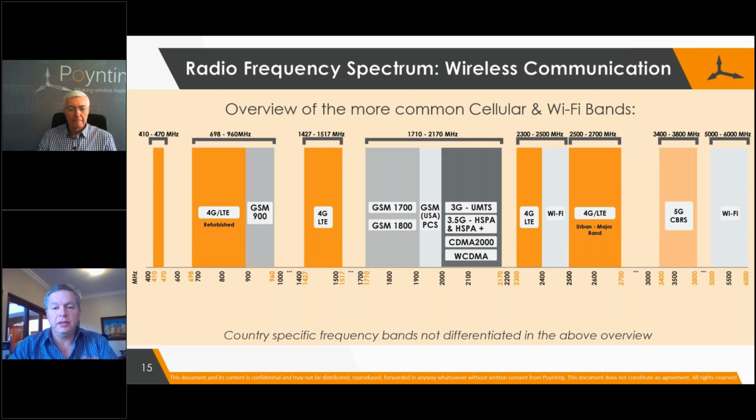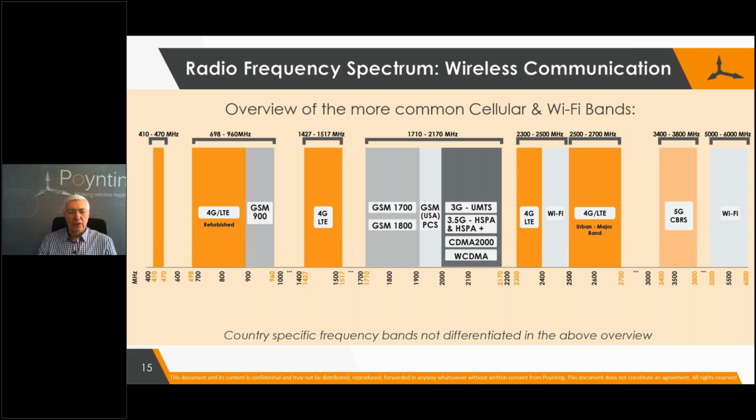So where you see GSM and UMTS right now could today be used as 4G or 5G frequency spectrum. So when you're looking at a 5G modem, for example, make sure that it covers all of those bands, because your operator may be using the 1800 or the 2100 band that was previously defined for GSM or 3G. So it's just something to take note of. Yeah, thank you, Stephen. Very important.